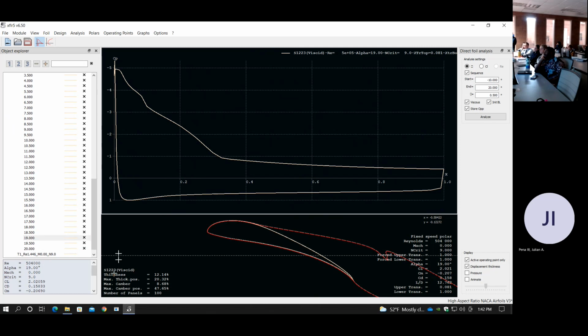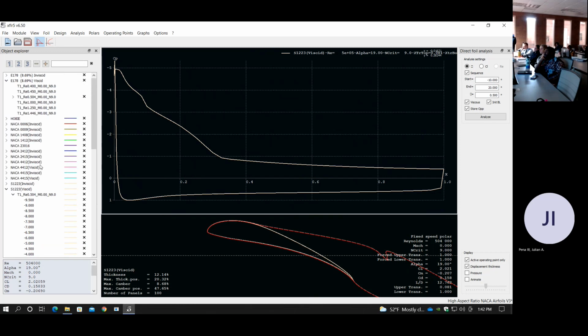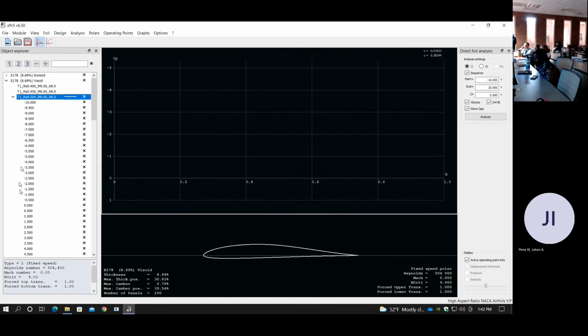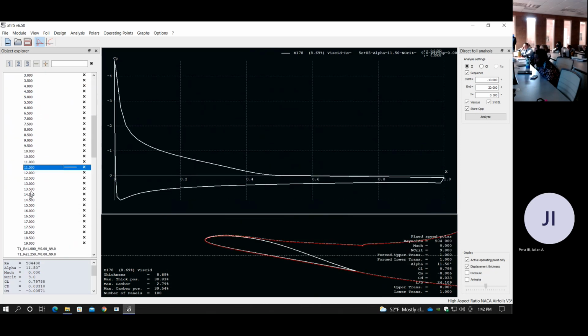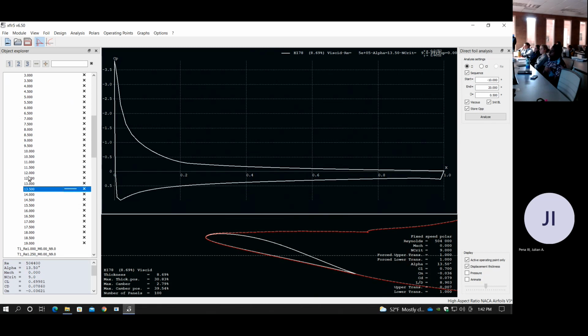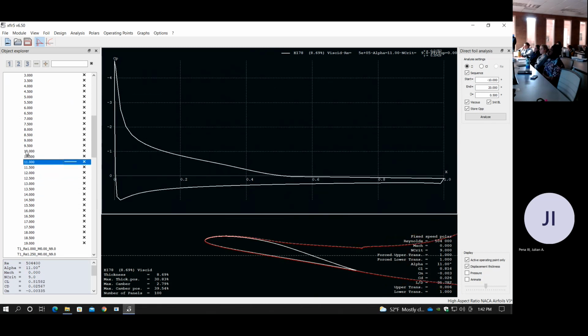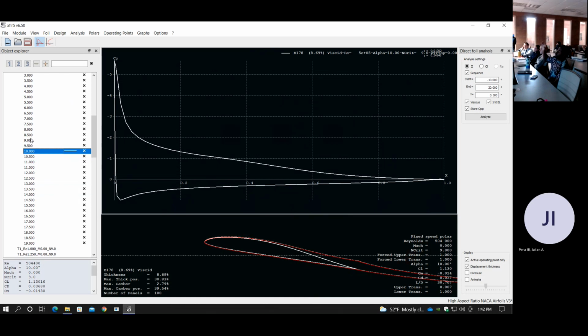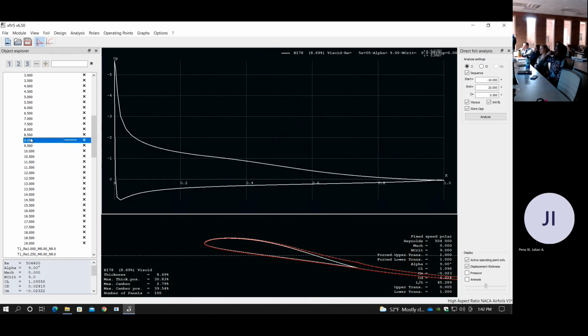And then if you take, for example, a less cambered airfoil, like your sailplane airfoil, at higher angles of attack, it doesn't separate as much. So yeah, I guess we'll move on to some 3D analysis, in which I will cover winglets.